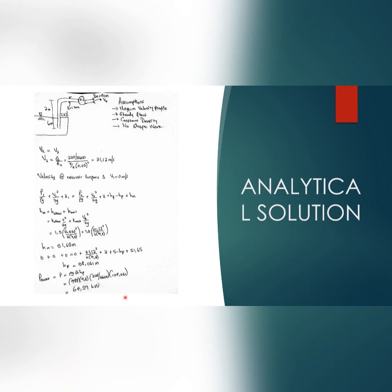Coming to the method of finding the answer, based on the assumptions above, we have implemented the continuity equation, as this is a one-dimensional flow, and also we included Bernoulli's equation due to no friction present on the flow, therefore no losses. Then we do the maths so that we can find the value of 64.59 kilowatts as our final answer.